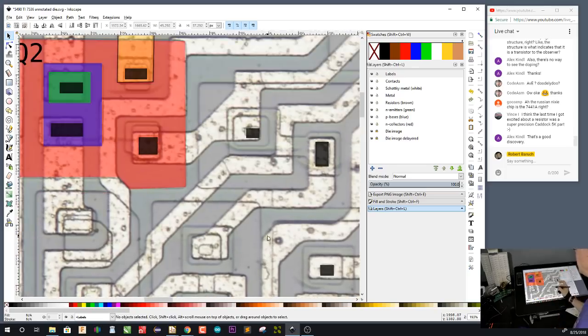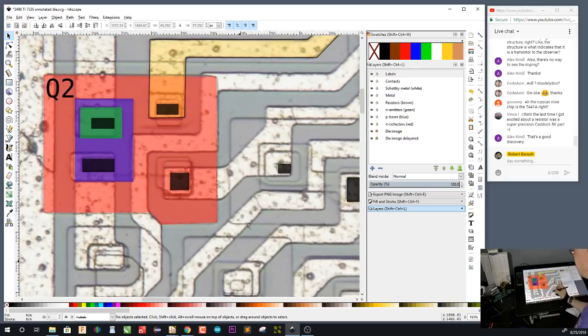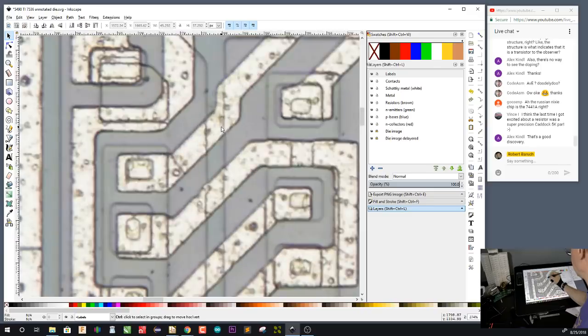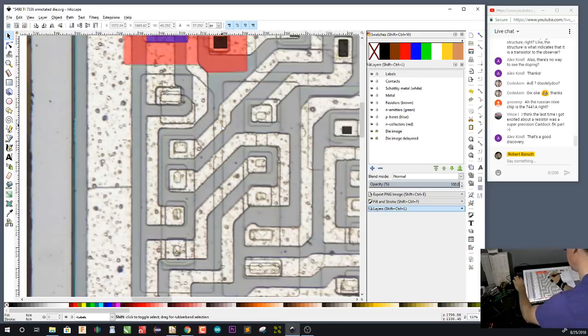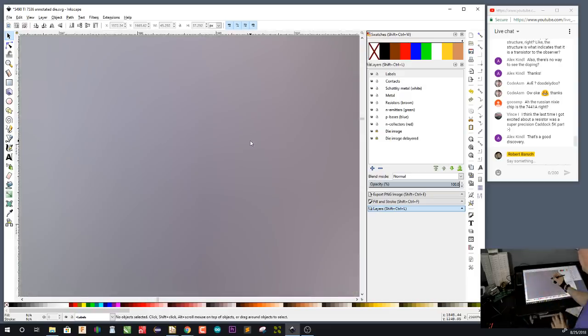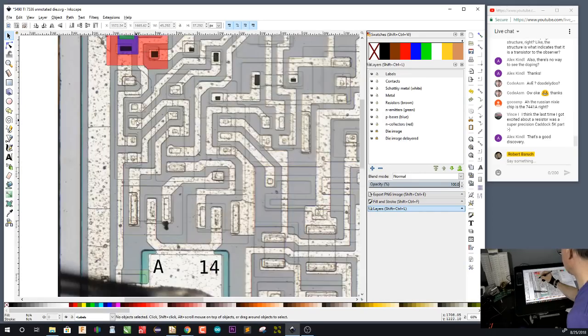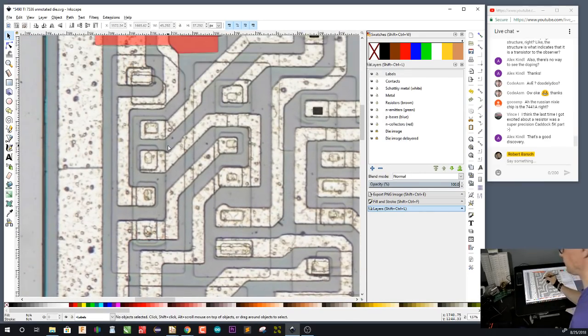Right, so what I was saying is that I usually go around and identify the collector regions first. So I think here's one. Let me zoom out one step. Oh, I totally screwed that up. There we go. Okay, so right here is an interesting transistor that I happen to know from experience is kind of a logic type transistor, in that it performs a logical function. So here's the collector on the outside. Let me go ahead and draw that out right now.